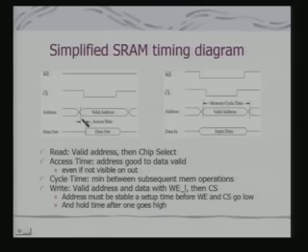The address is provided on the bus. The decoder would be typically part of the memory device itself for selecting the row. So, that means once I have selected the corresponding memory module and I have provided the valid address, the row would be selected, and after that you will be expecting the data. So, this is the time difference between the address becoming valid and you receiving the valid data.